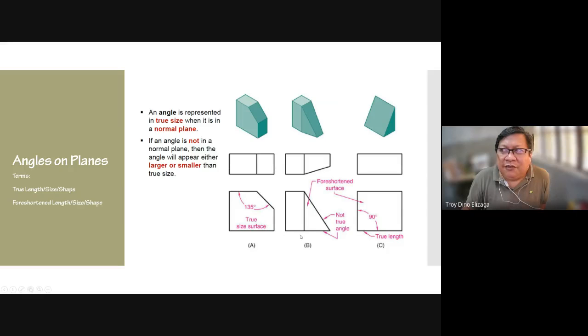Now, this is very useful when you are trying to analyze roofing, especially if you're not using flat roofs. In the Philippines, we're not supposed to be using a lot of flat roofs because we are in a tropical country and we're just inviting problems when we make use of flat roofs. It will be prone to leaking.